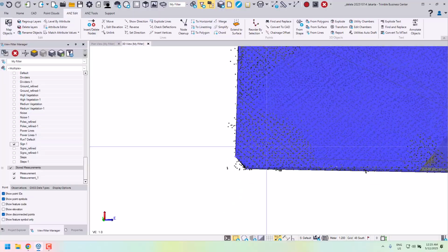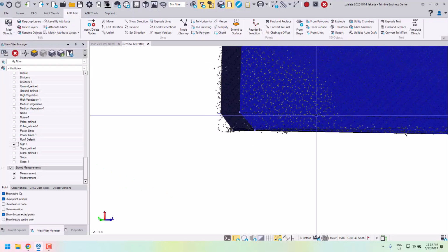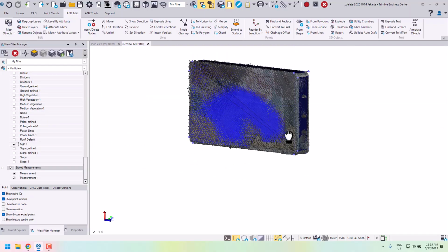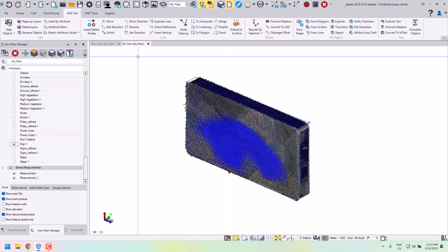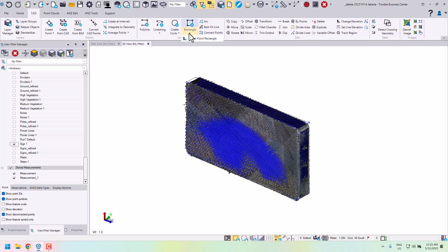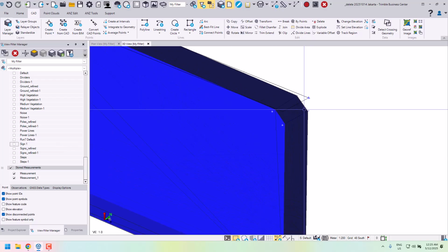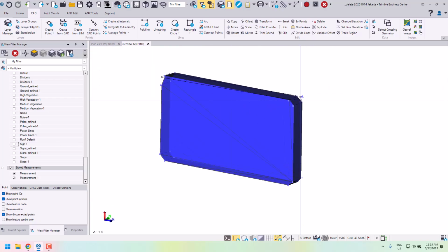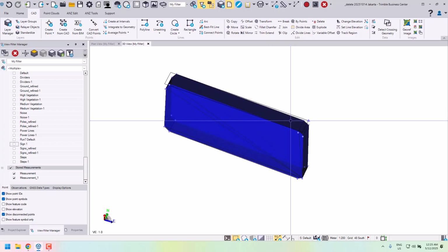I haven't taken too much time in digitizing, but that really gives us 3 distinct ways of doing it. We can start with 3-point rectangle. We can move to the outline tool under line string, and then we can generate multiple line strings and run the extrusion through and be able to do it that way.